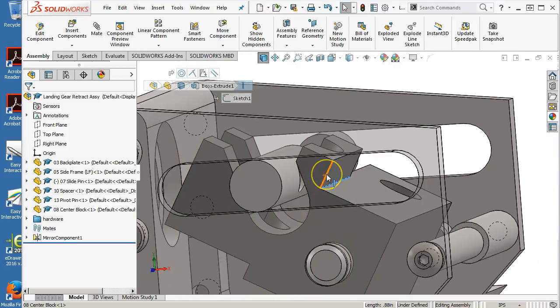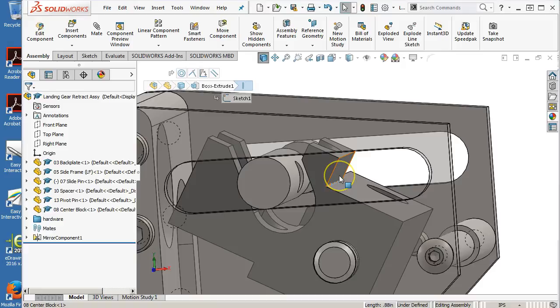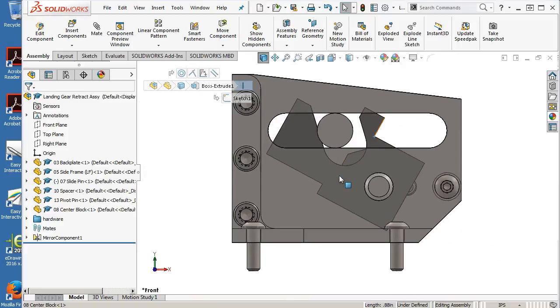So if I was going to do FEA on something, this would be it. This is a major stress riser. Putting a radius in and thickening up that cross section is going to go a long way toward building in additional strength. Okay, so when we jump over into the FEA, this is a prime candidate.